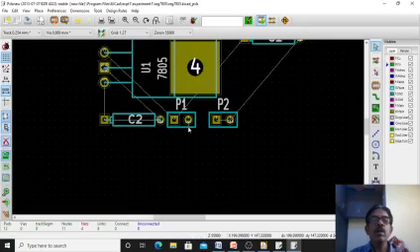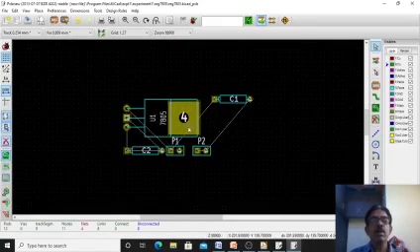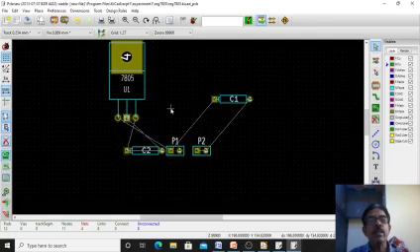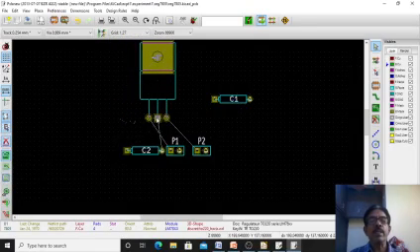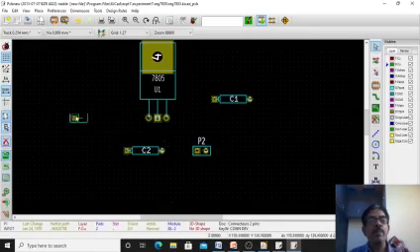Now these white wires were there, they are called ratsnest wires. Now arrange these, okay, properly. First, let us, I will begin with the 7805 IC. You rotate it, okay, and place anywhere you want. For placing you first move, place it like this. Then I know P1 is on the left side, so take this P1, you say M means move.